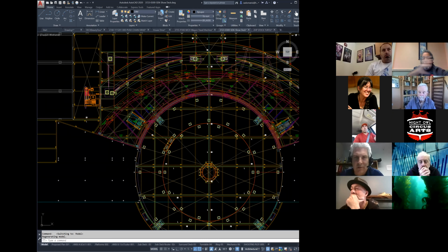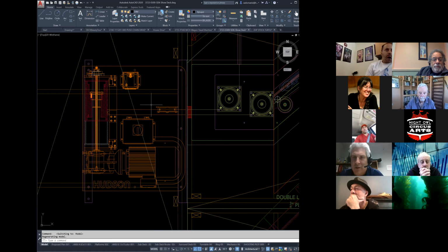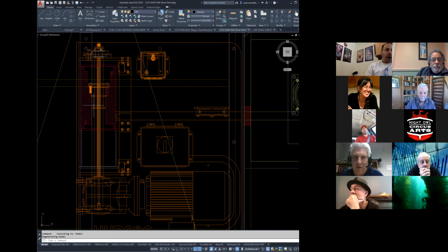Yeah, this actually is a little better, clearer picture of the same idea, but this is a slightly different model of that machine. This machine sits stationary. You can see our grooved drum here, and you can see the red image is the drum at one end of its travel, and this gray outline is the drum at the other end of its travel. The cables are always coming in at this one location right here, and as this drum rotates, the machine is all stationary and just the drum is moving back and forth on this special splined shaft as it rotates. That means we don't have to worry about those fleet problems.